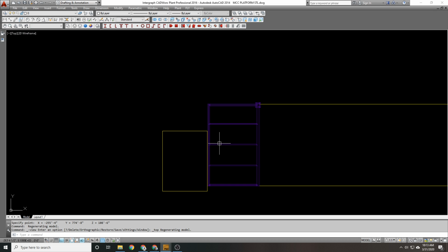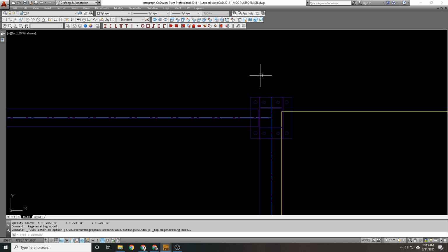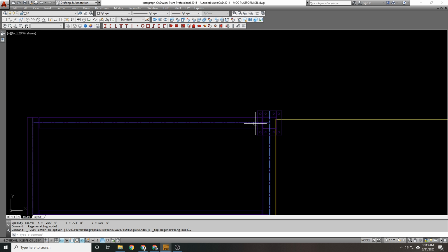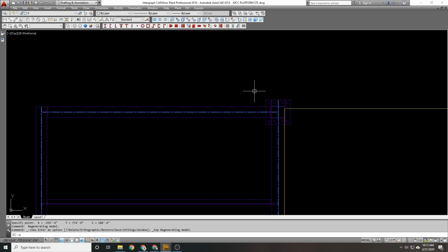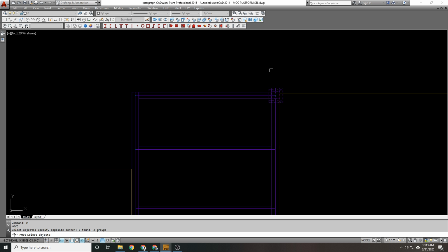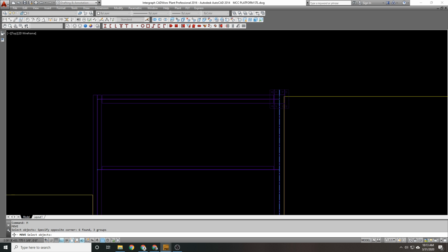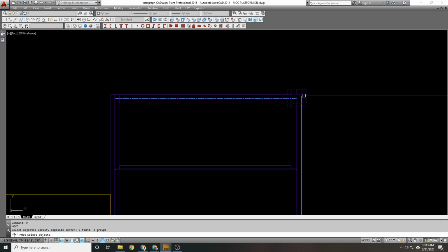And it's funny, this happens a lot. And I'm kind of glad this happened actually. I did all this work for this beam and realized this isn't even going to be where the beam is connected or the column's connected, because I kind of get lost in a one track, and then I go back and look and realize, oh yeah, that's not what I meant. I actually forgot that here. This isn't what I meant for it to be. I want to move that in. So I have 9'8", so I want to move this in, I don't know, maybe 2'4" would be good.